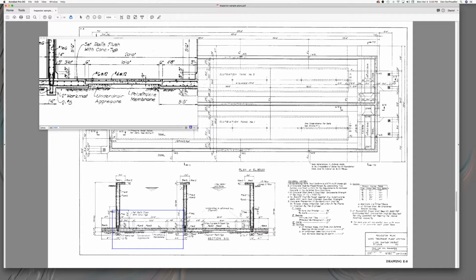If I had to choose, and I don't know what the ABCD is, hopefully they didn't have A as polyurethane, 2 as under drain aggregate, 3 as 2-inch work mat, and D as sub-base material or earth. If they had it that way, it would be easy. You just look and see the polyurethane arrow goes right to the underside of the slab.